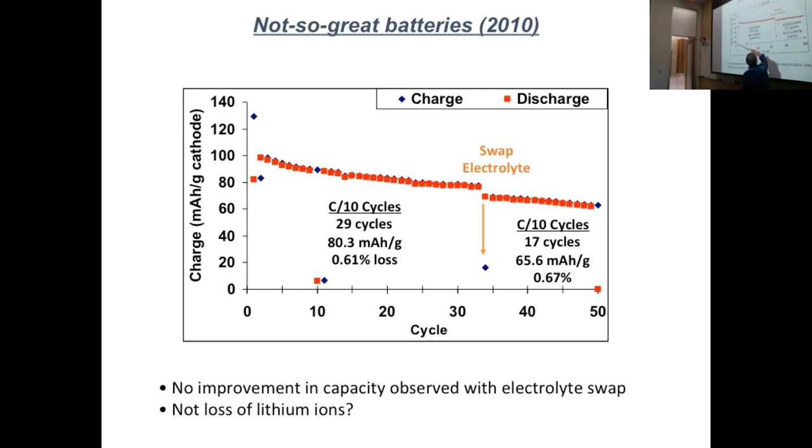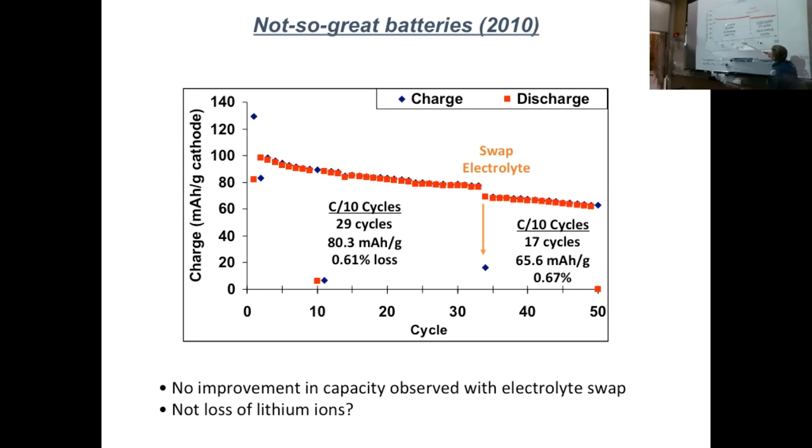So you don't have to really worry about that. But then effectively what we do is we look at how much energy can we store. So milliampere hours is charge. It's current times a time, so that's a charge. And we normalize it by the weight of the cathode so that we basically account for variability in the cathode mass between different samples. And what we essentially do then is characterize how does this vary as a function of the number of charges, and we can do it at different rates.